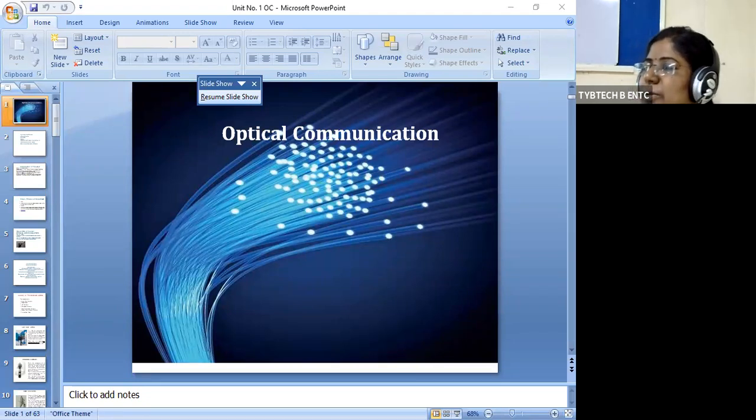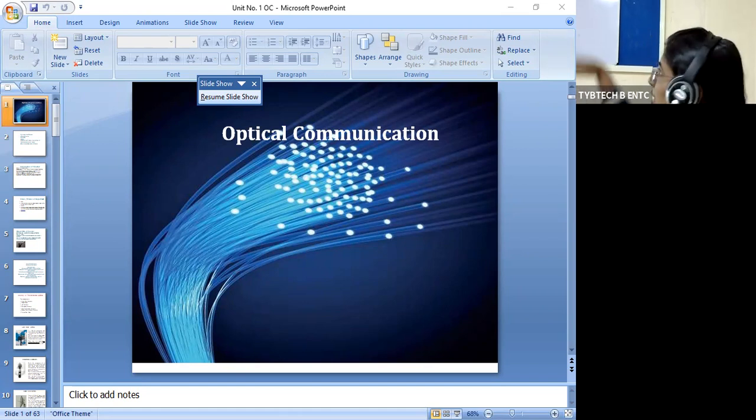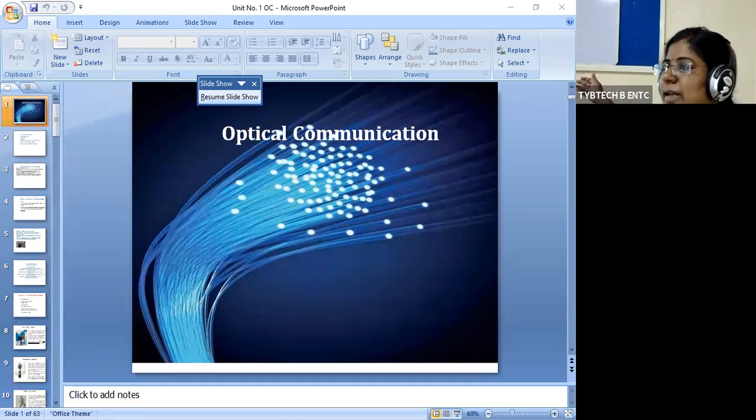If you look at the optical fiber structure, the core is there and it is surrounded by cladding. So whatever light is transmitting, it transmits through the core only and does not enter the cladding. You can call the cladding a protective layer for the core, because it is basically protecting the light transmitting through the core. There is reflection there, so even if the light tries to go out of the core, at the core-cladding boundary, as I gave you an example yesterday: suppose this classroom is the core of the optical fiber, and that wall is acting as a core-cladding interface.